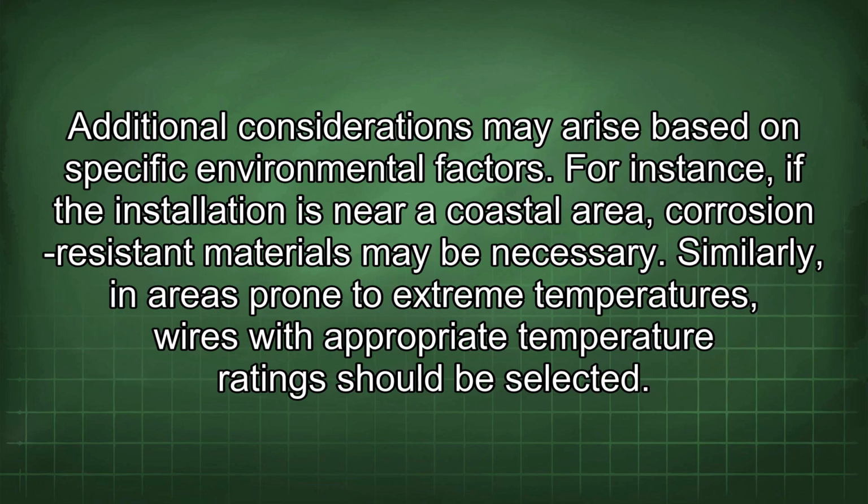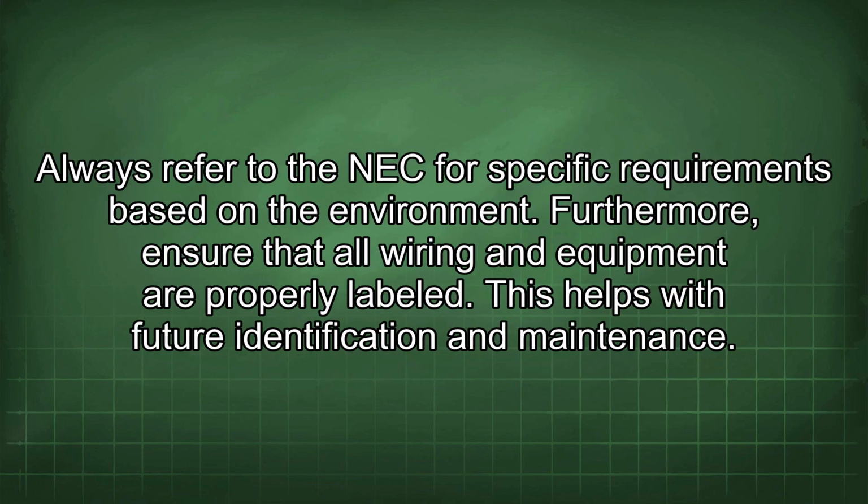Additional considerations may arise based on specific environmental factors. For instance, if the installation is near a coastal area, corrosion-resistant materials may be necessary. Similarly, in areas prone to extreme temperatures, wires with appropriate temperature rating should be selected. Always refer to the NEC for specific requirements based on the environment.